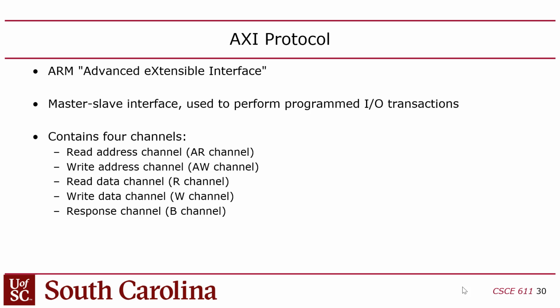It's an addressable bus. You can read or write, right? It has a coordinate addressing system, right? So AXI has, and there's actually another version called AXI Lite that's a little simpler. But what I'm talking about here is the full AXI. This is the full strength AXI bus, and it has four channels. Sorry, five channels.